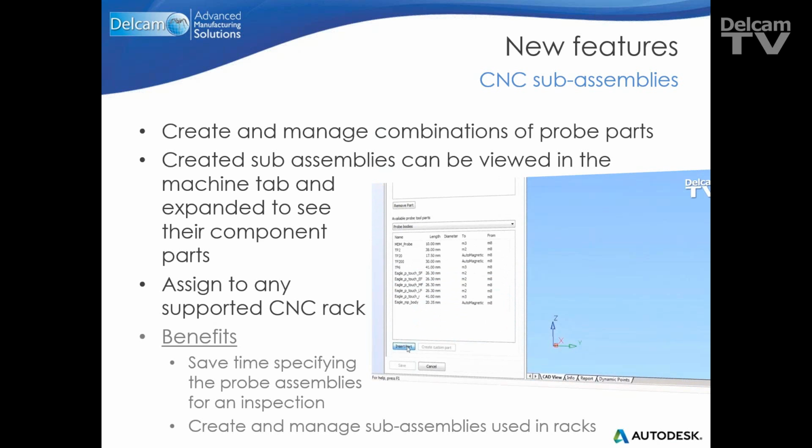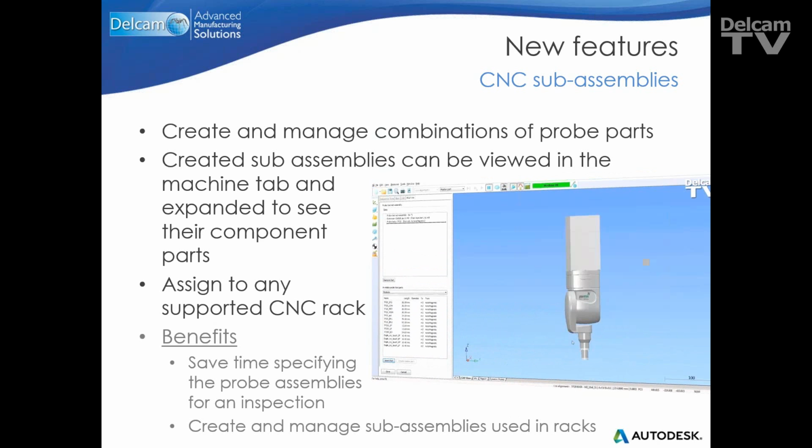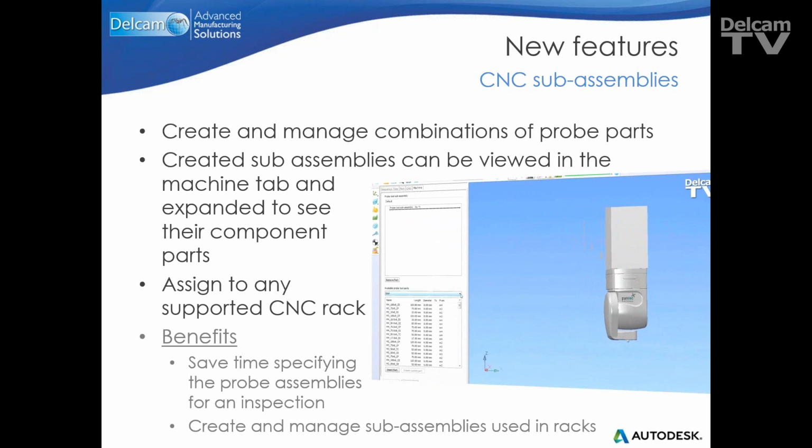First I'm going to select the extension for the probe body as seen on the screen. Next I need to create a sub-assembly for the probe module. To do this I select the correct module alongside any other extension, as well as selecting the appropriate styli for the sub-assembly. Okay, now you'll also notice that during this build-up phase that the items being built up started at an initial mounting point, and that's what I refer to as a static sub-assembly.